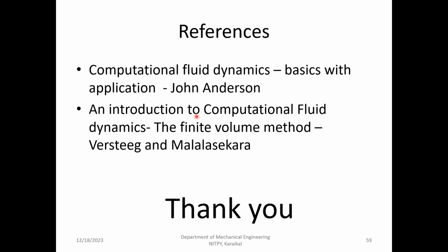The thing is, when you're going to go with meshing, my guide used to say meshing is more of an art than a science. When you ask for proximity and curvature, all those things, the machine will do some mesh, but it will take longer time. So generally you can divide. In my case, I will divide my domain into smaller domains, and I will always use hard fixed dimensions.